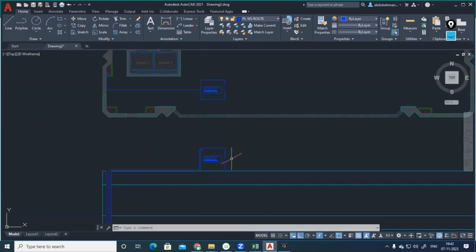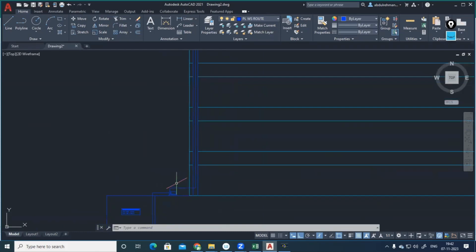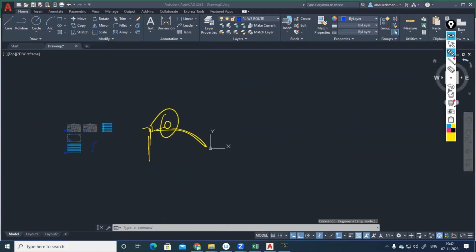Any other valve? See, for every pump, some standard fittings are there. Standard, so that is common for almost all pumps. Pump suction side and the pump delivery side. Anyhow, if it's a negative suction, foot valve will come. Positive suction, only strainer. But normally for a standard pump, there is the pump suction line and pump delivery line.